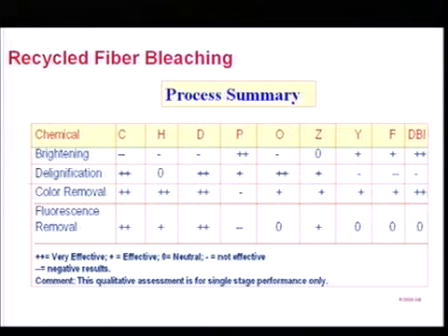Peroxide is not that great a chemical for decolorization, but it is an excellent brightening chemical. Oxygen, okay, not as effective as chlorine or hypo, same as ozone. Again, hydrosulfide and FAS are not as effective as chlorinated compounds, but DBI is much more powerful because of the various reductive species available there: bisulfite, borohydride, and also hydrosulfide.